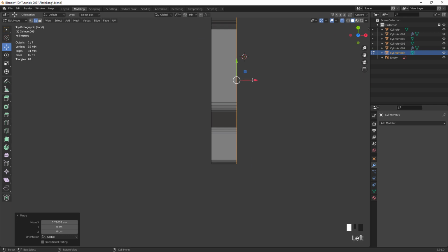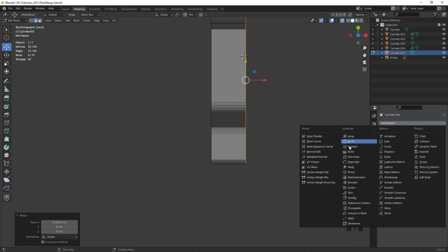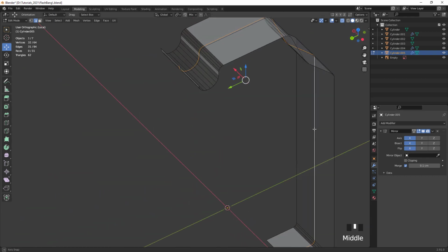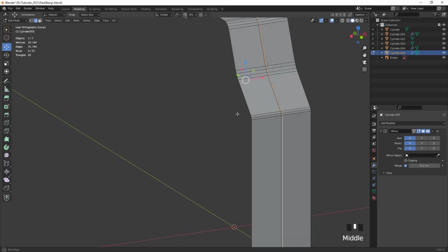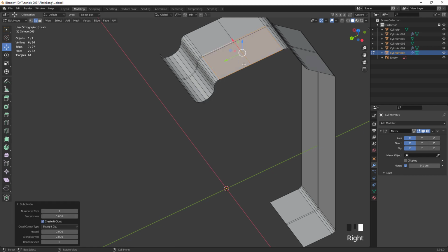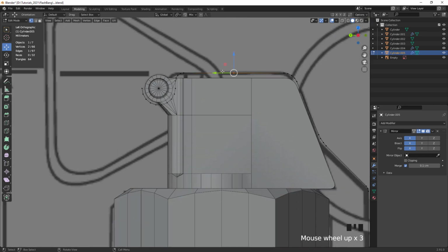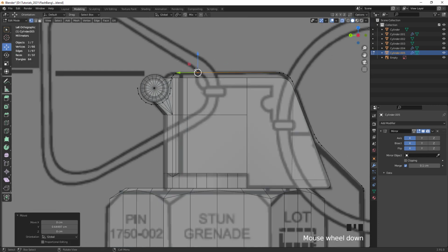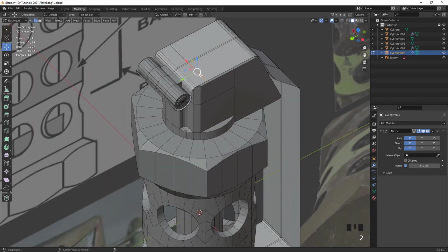And then we're gonna take this here into the center and put the mirror modifier on. I put it to bisect and flip on the X, and essentially now we have this shape here with some volume. I'm just gonna subdivide it here so that we have a bit more polys to work with. I'm going to take these vertex points and put it here where we see on the reference that we have an object coming out of there, or another element.